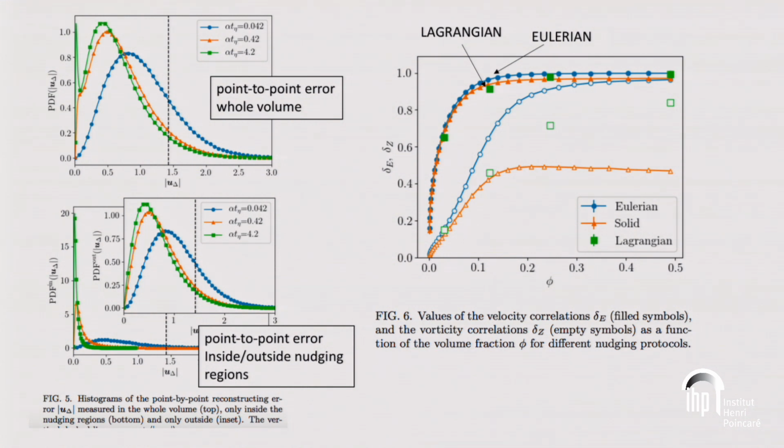And you see that this is the mean value of the velocity, and the errors are nevertheless always much smaller than the mean value, and then you can eventually quantify how good your reconstruction is by extracting a posteriori also an estimate of your error.